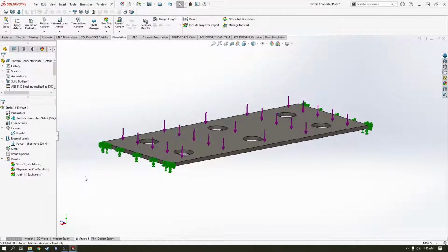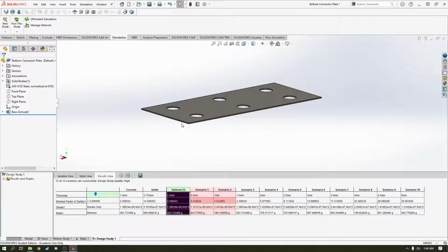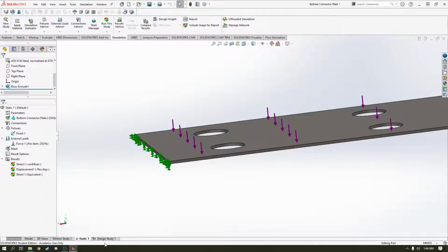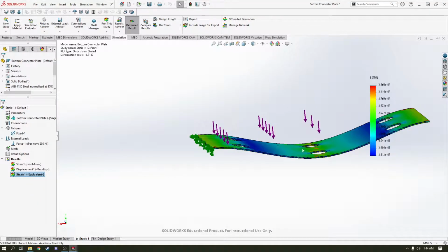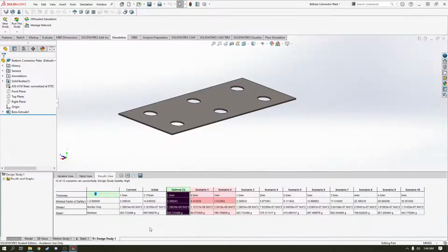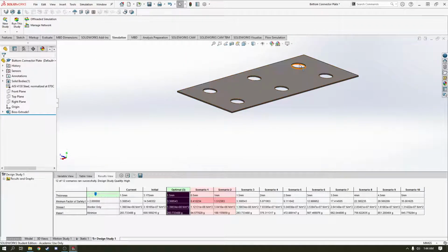And then when you come to static study, when you mouse back over to this tab, it should keep the dimensions of the most recent one that you clicked. Yes, see, now it's a bit thinner. And then you can get your diagrams and everything for this specific iteration. So here's your optimal thickness. It's apparently 1.5 millimeters. So that's how you set that up.